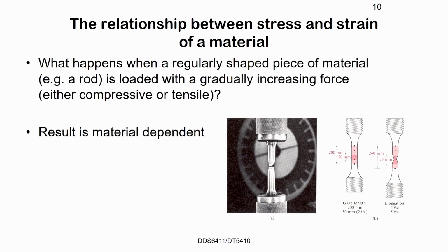I was going to explain this again. Because of necking: under plastic deformation, volume is conserved. So when you increase dimension in one direction, you have to reduce dimension in the transverse direction. We're having the same volume, it's increasing in the axial direction, so it needs to reduce in the transverse direction. That's why we have necking. So where would necking be? Beyond here. The moment we produce plastic deformation, we're going to get necking.